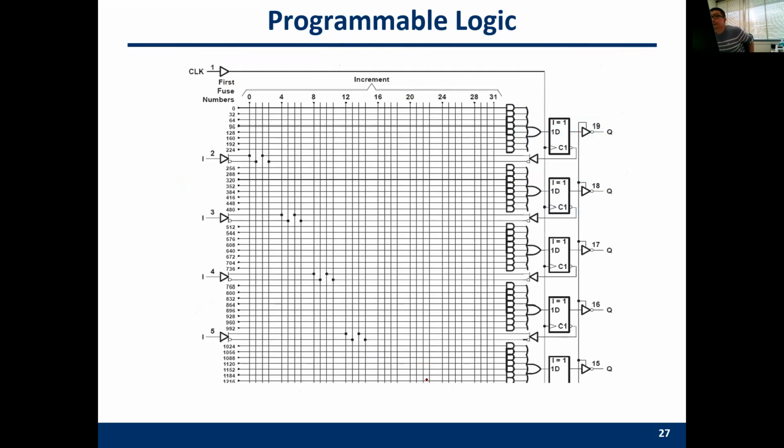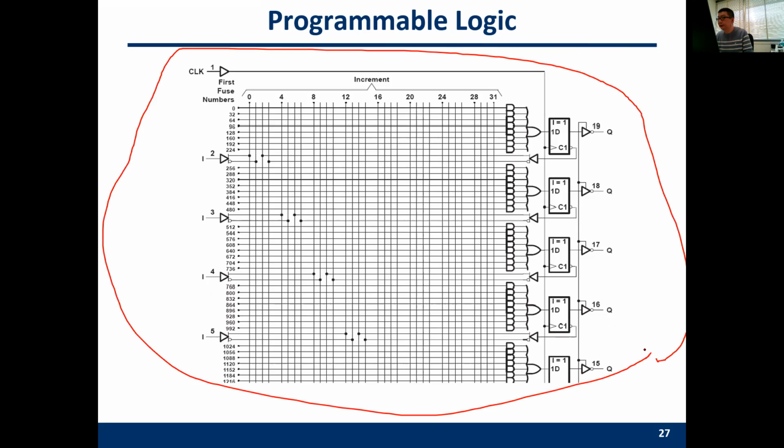So this is the so-called prototype of a reconfigurable logic, which is also the prototype of the FPGA. But for the real FPGA, we have more complex connections. And this one is actually a complex version of this one. So you can see we have a lot of inputs here. We have a lot of AND gates and OR gates here. We also have this so-called latch. D latch can temporarily store the output of this OR gate.